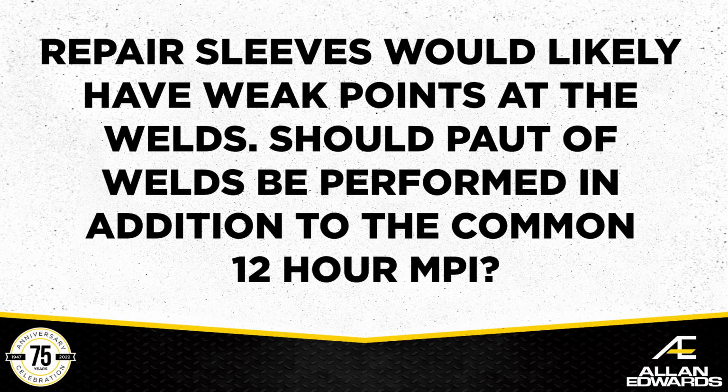The next question is, repair sleeves would likely have weak points at the welds. Should PAUT of welds be performed in addition to the common 12-hour MPI? That's more of an industry question, more of an installation one. David, do you have any thoughts on that? Yeah, so that comes down to the operator, right? Code tells you that you have to inspect your sleeves for features that may form due to the heat and the cooling of the weld metal, right?